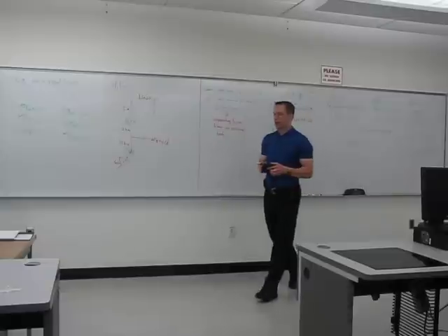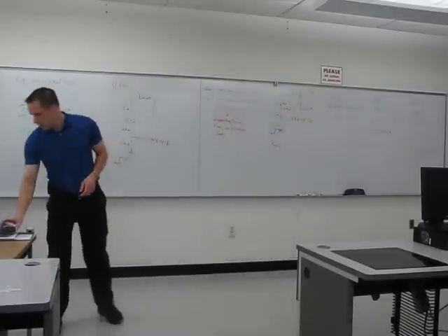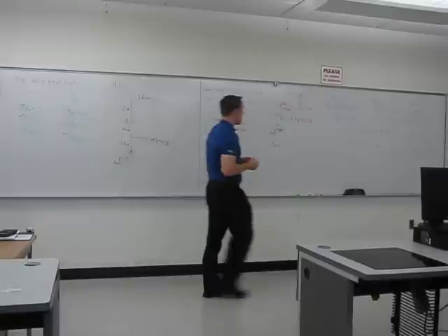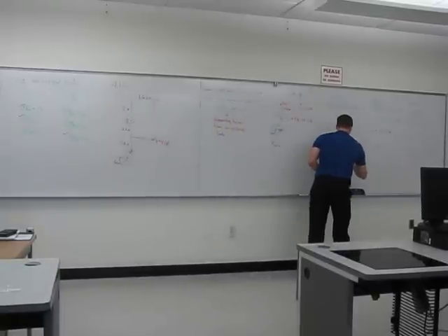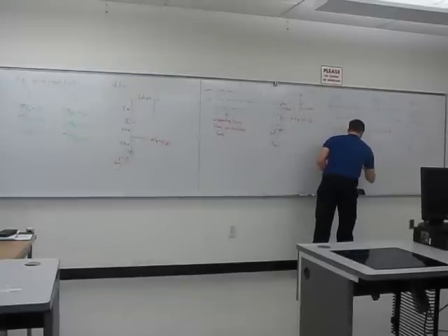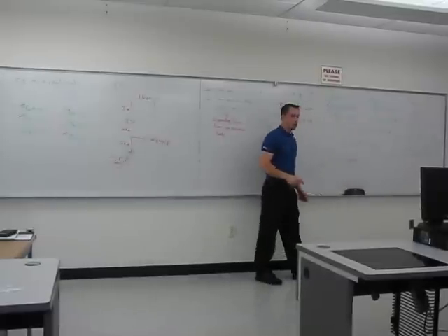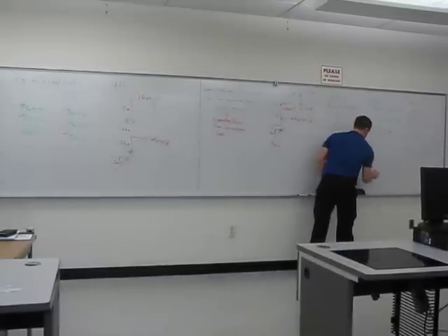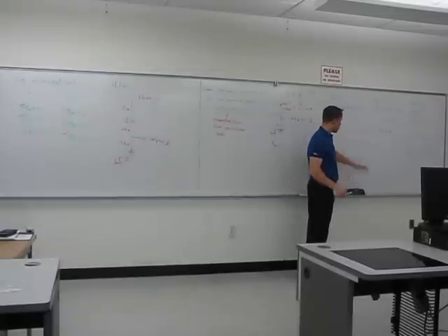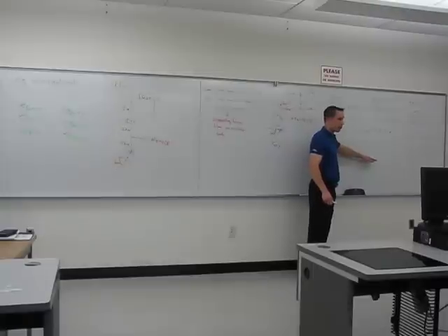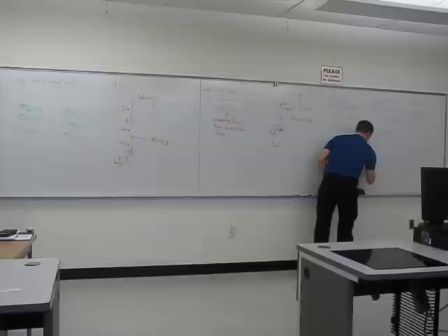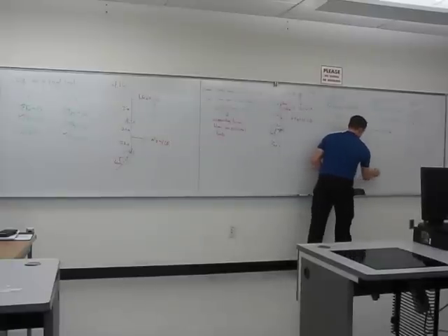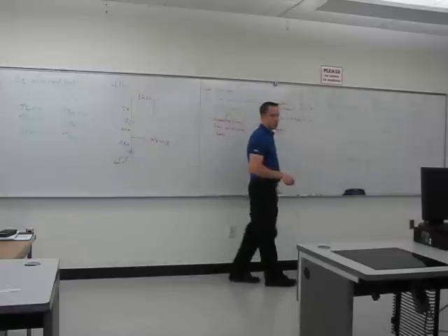So to put this into the vector form, we would say that FC, the vector, is equal to 8.05 pounds. And because the x and the y components were negative, we said that FC is actually angled into the third quadrant, so I show my angle going into the third quadrant, and that 6.6 degrees means from the horizontal reference we go in a counterclockwise rotation by 6.6 degrees. So that puts you down in the third quadrant there. So that's what we call the reaction force at C.